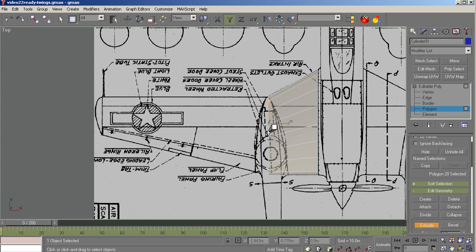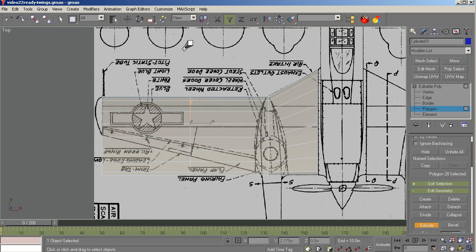There we go. And we're just going to extrude out about halfway, and the reason I'm stopping at about halfway is that if you have very long polys with no breaks, with no cross sections, you'll end up with some shading issues where you can actually see where these lines join. The smoothing won't be as effective. So I usually give it at least one or two breaks here. So now we're running out to the wingtip or root. Right there. Now we're ready to shape.